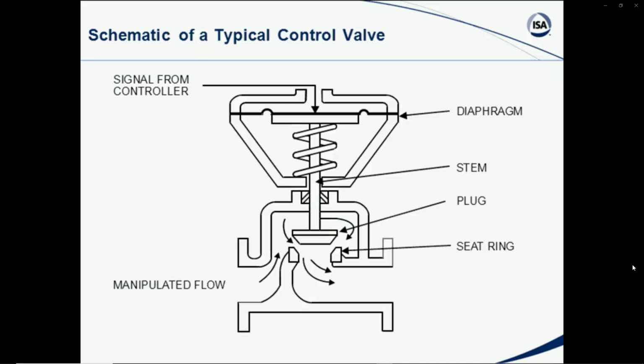One other final piece of information on a typical valve, in this particular case which is a linear rising stem operation, is packing. This is the packing polymer that compresses some material around the stem to allow the stem its linear motion, but at the same time to seal off from the atmosphere the exposure to any of the materials inside the valve.